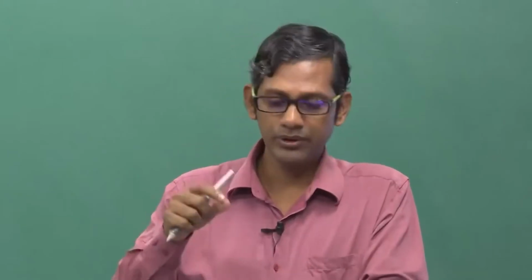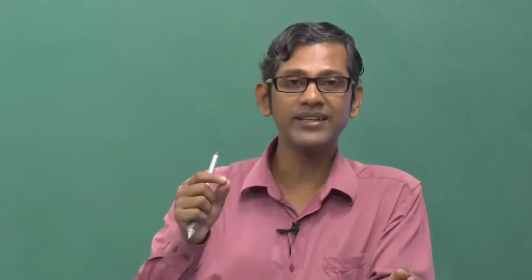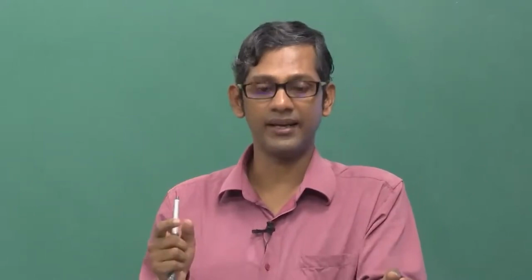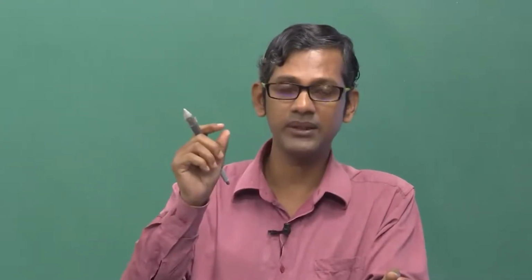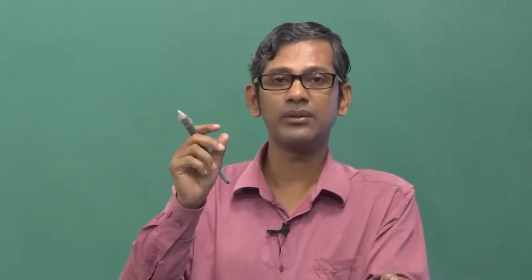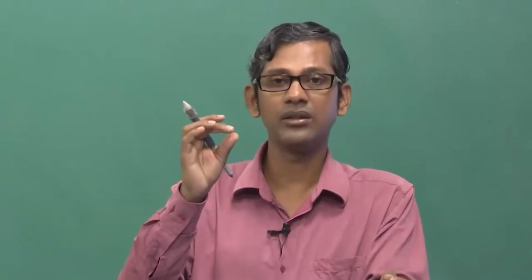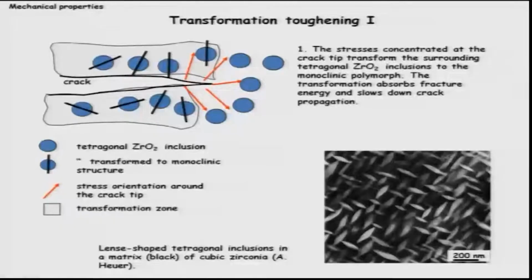concentration. Why? Because the load is the same. So if the size is small, the area is small, and the stress is higher, because the crack tip is a very thin layer. So the surface area is very small. Therefore, there will be stress concentrations, and these stress concentration regions at the tips transform the surrounding zirconium oxide particles or